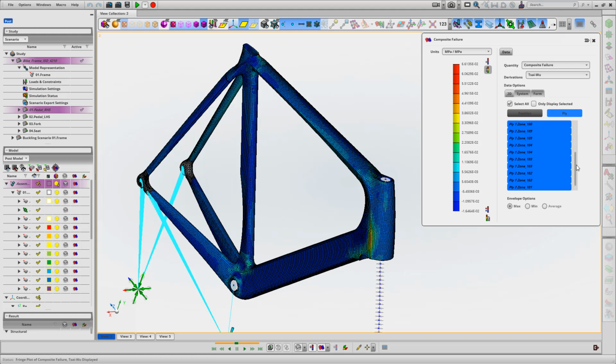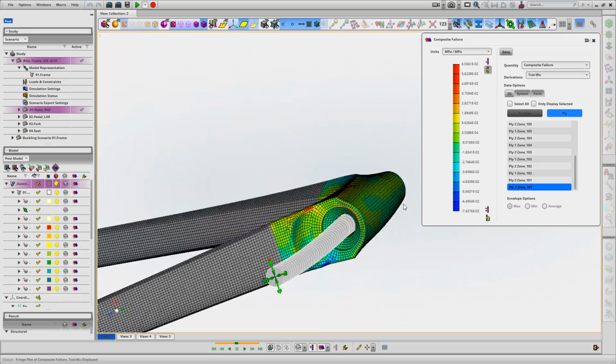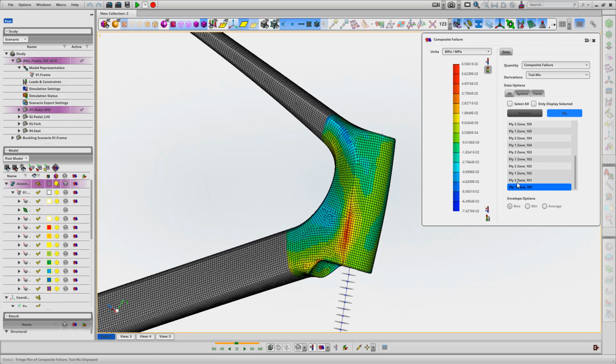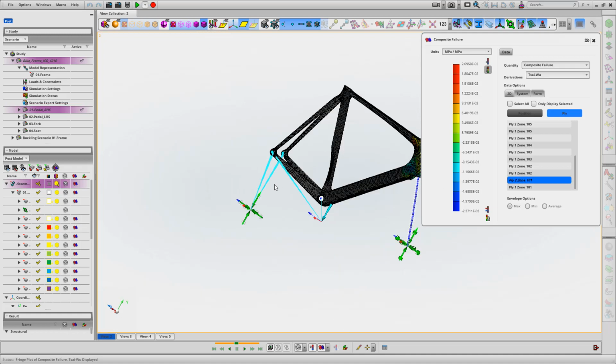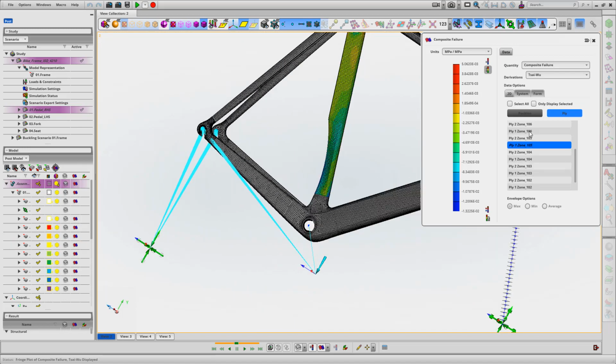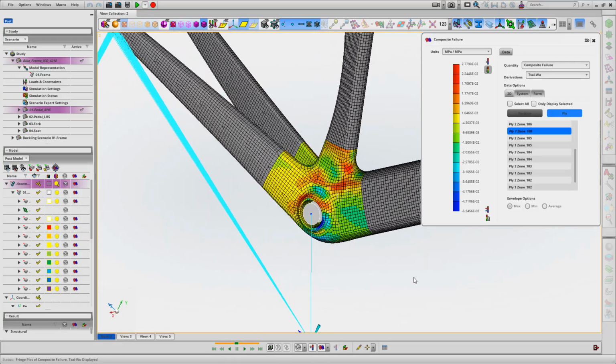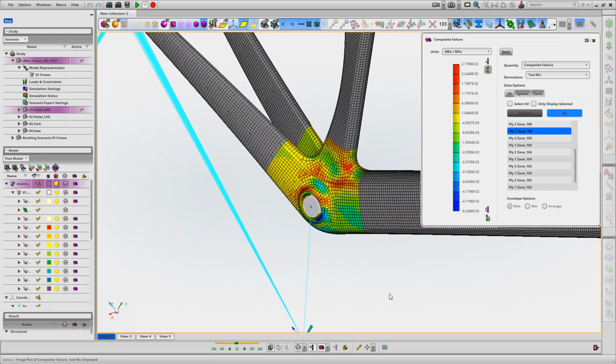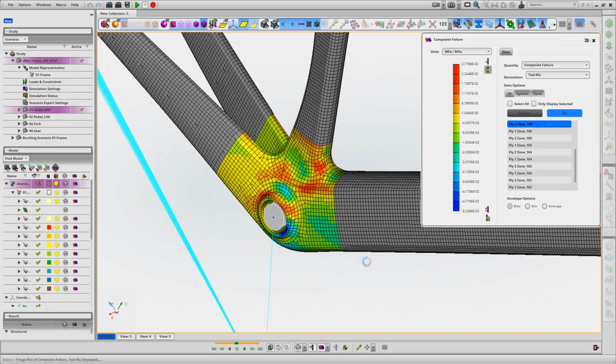We've got the ability to look at these strength outputs on discrete regions within the model. So given our zone definition, so this might be reflective of the build sequence for the composite structure, and we can look at which type of plies and materials and how they're loaded and how they'll influence the overall structure. Obviously lots of information here, so pretty complex to assess or to update from an optimization perspective, which we'll come on to in a moment. But we can see the discrete behavior of each one of these output quantities for our given ply stacking sequence and laminate. Okay.